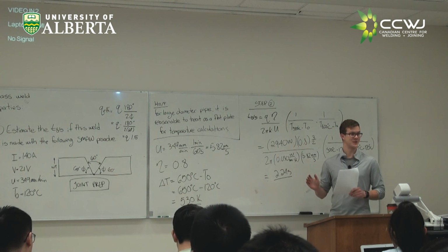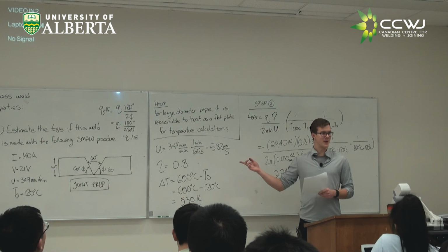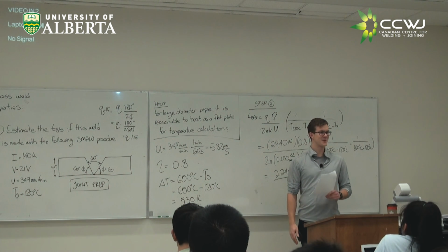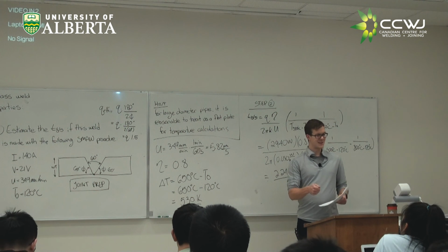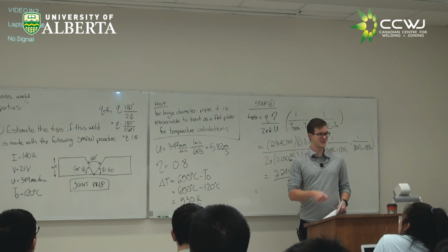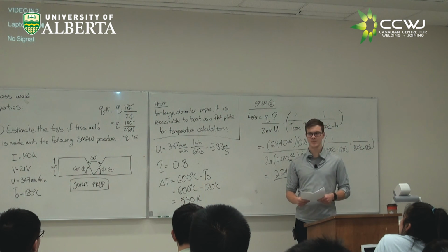It's extremely powerful, the equations you're learning here. And these are not equations that everyone working in industry necessarily has. A lot of people who would make a weld on this pipe just know from experience that if they weld with about 140 amps and 20 volts and move so fast, it's going to be okay. And the welder, as he's welding it, knows that if he's welding too slow, it looks like the puddle's about to fall on his feet. And if he's welding too fast, you can see holes in his weld, and he moves at the speed that makes sense for him.